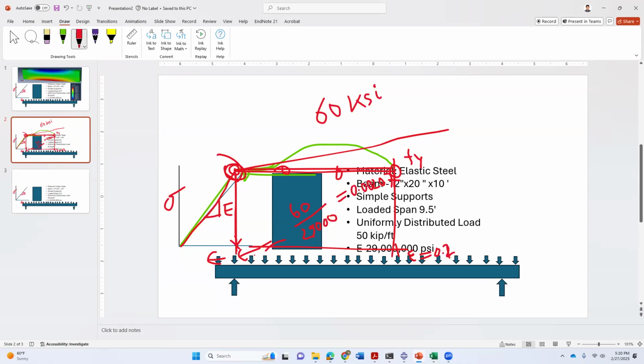So this corresponding plastic strain means total strain minus elastic strain, which can be calculated by subtracting the elastic strain from the total strain. So from that total strain, you need to subtract 0.00207 to get the plastic strain, which is not a lot. So I just use this total strain as a plastic strain.